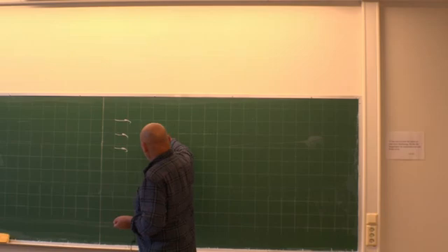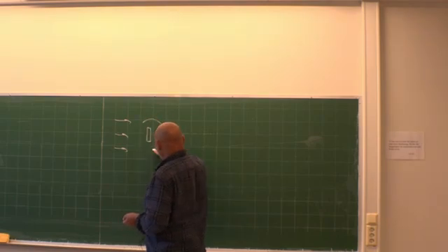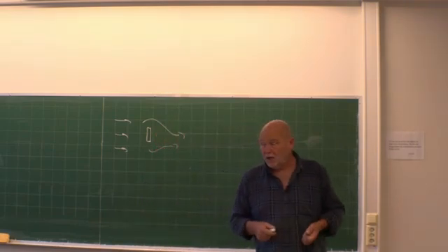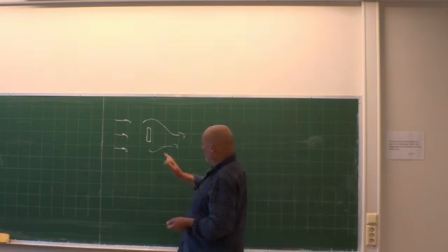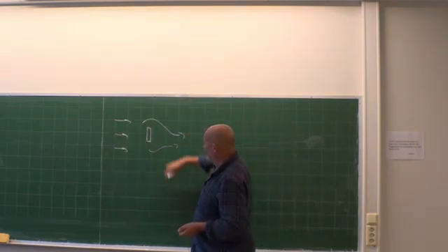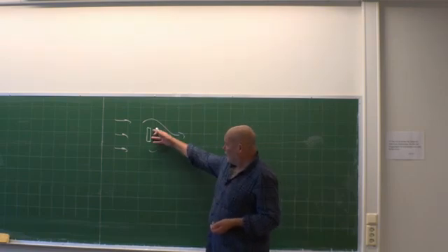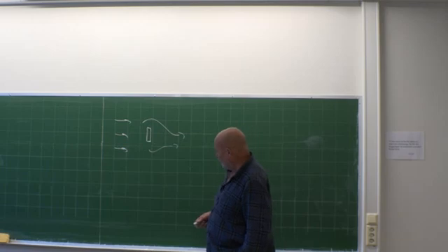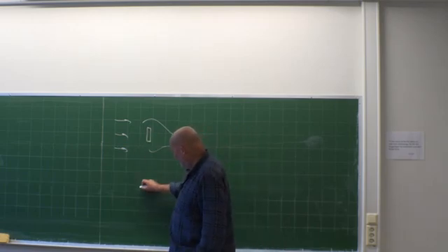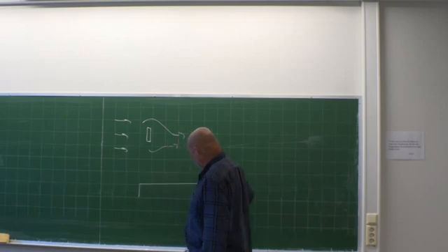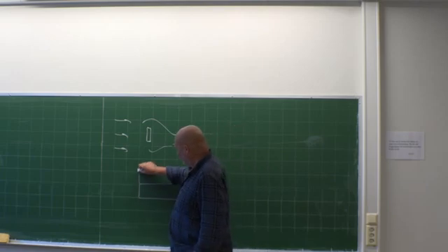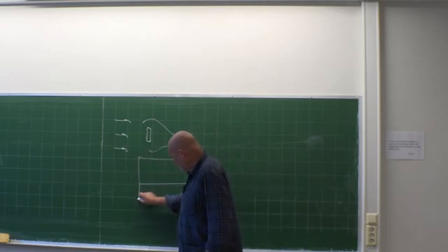So here I have a plate, and the flow should go around this one quite nicely. I'm not interested in what's happening in front of this plate or over and under, but after this plate I want to see what's going to happen. So I did this very brutally for the plate. I just had one block here, and then over and under, I created some other blocks.